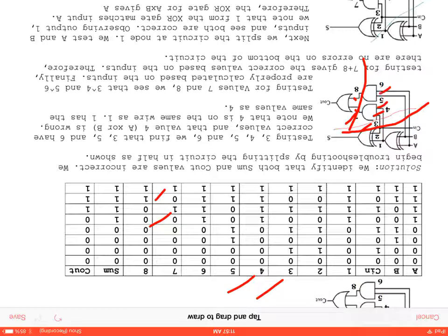We go through, and we do see that 8 is equal to 5 and 6. So we know that our AND gates are not the problem. And we see, is C out equal to 7 or 8? We check that, and sure enough, it is. So we have also eliminated the OR gate as the problem. So we now know that this half of the circuit is fine.